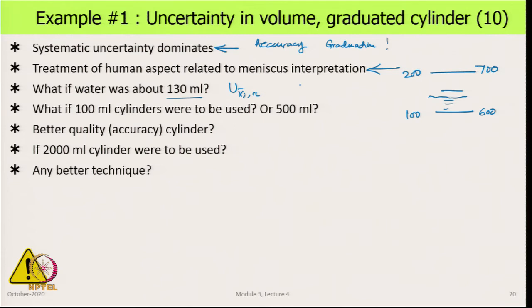But the issue then becomes the relative uncertainty, this will be much more. Instead of 4.5%, we are looking at roughly 5 times larger, almost like 20-21% uncertainty. That is a big uncertainty, and it tells you that is not a nice thing to have. This sort of uncertainty one generally does not like to have in any measurement. Do not use this cylinder, go for some other option.